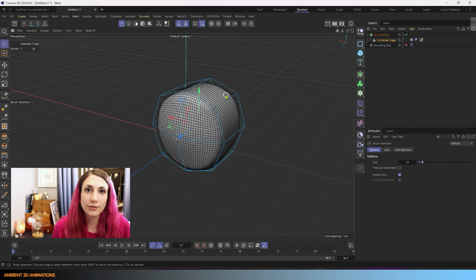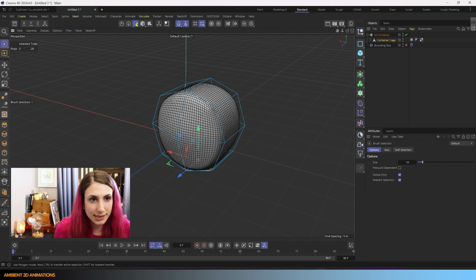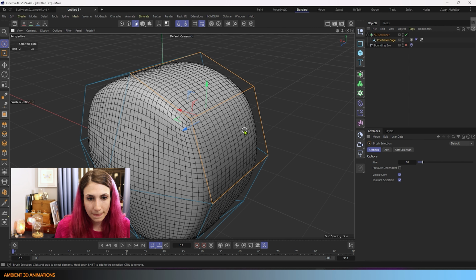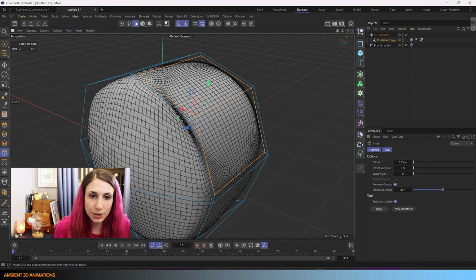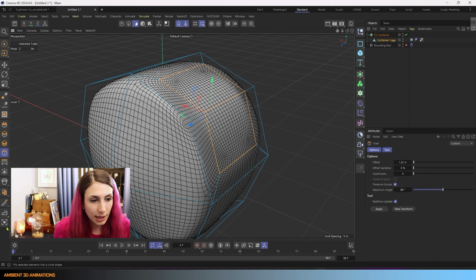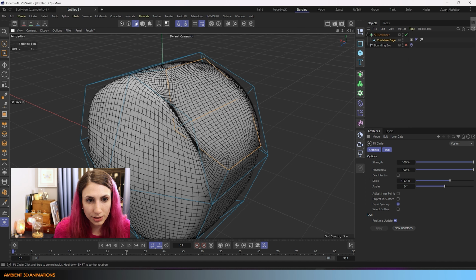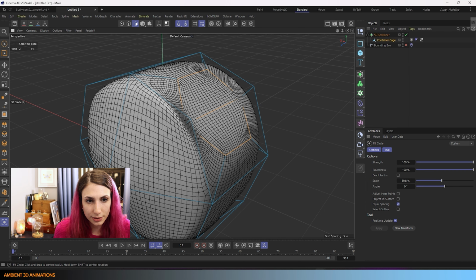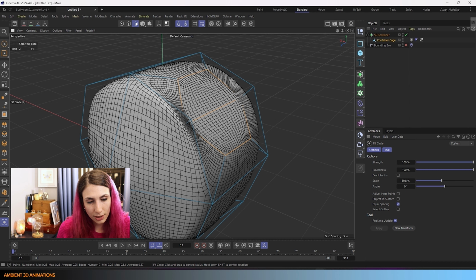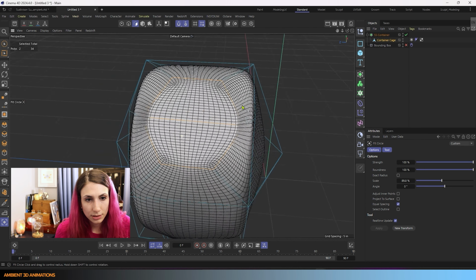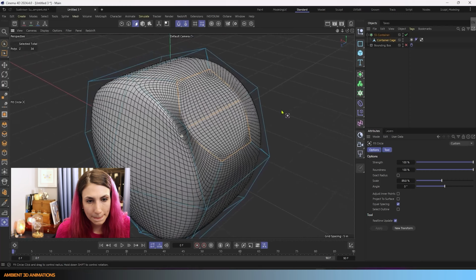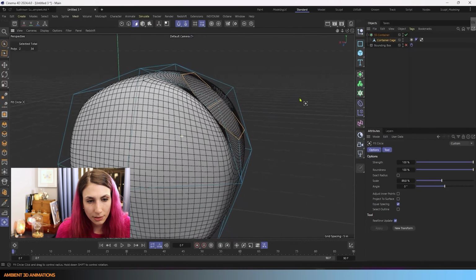Now we need the opening for the container. So I'm going to go back into polygon mode up here. I'll click here and I'll click here. And I'll use MW in order to inset this. And I'll use fit circle, click and drag out here in order to create a circle here. Now I want to weight this circle and round it out a little bit. So this is looking better.